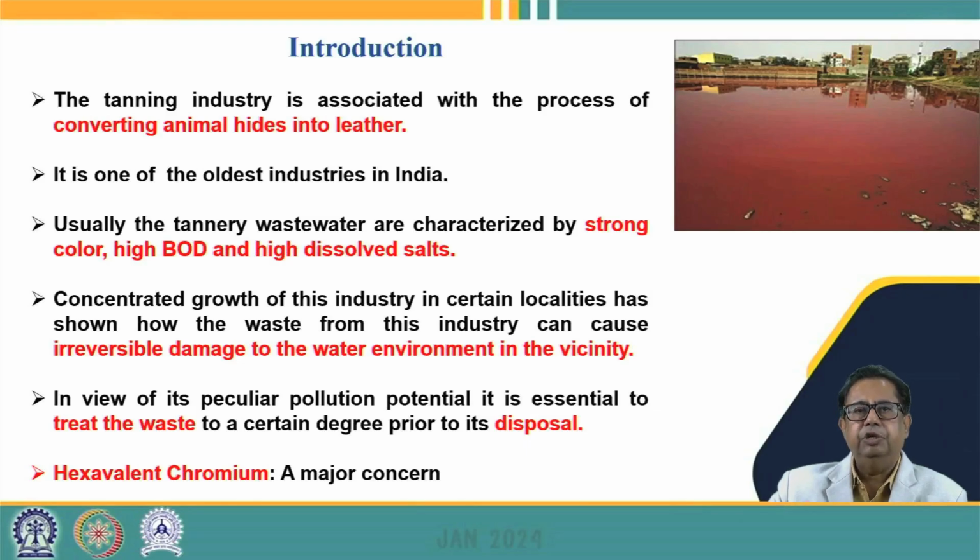And similarly, the pH will vary depending upon what process we are using. The wastewater coming out from that process, the pH will depend upon that process and the chemicals that we are using for it. The pH may be basic when we are using lime salts, whereas it can be highly acidic when we are using acids and other acidic salts.